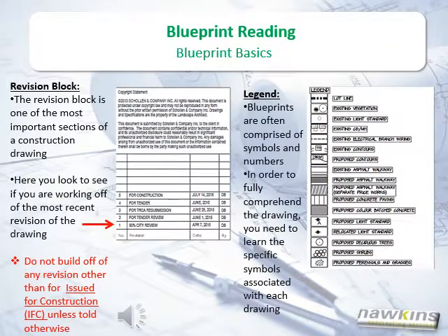Other aspects of a drawing are the revision block. The revision block is one of the most important sections of a construction drawing. Here you have to look to see if you are working off the most recent version of the drawing. Do not build off any revision other than issued for construction unless told otherwise.